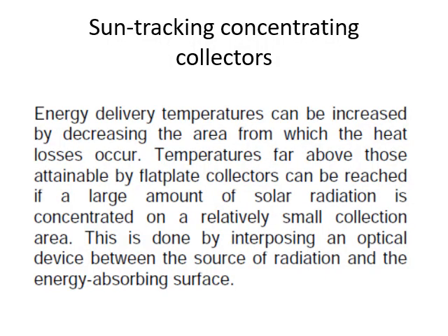So we have seen previously the parabolic concentrator, right? We didn't really have to do the tracking of the sun. But if you really want a very precise one, and you want to capture all the sunlight throughout the day, you should incorporate sun tracking collectors. So this energy delivery temperature can be increased, and if you can decrease the area from which the heat losses occur, temperatures far above those attainable by the flat plate collectors can be reached if a large amount of solar irradiation is concentrated.